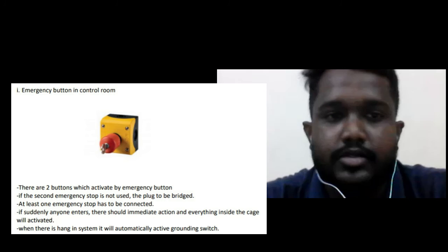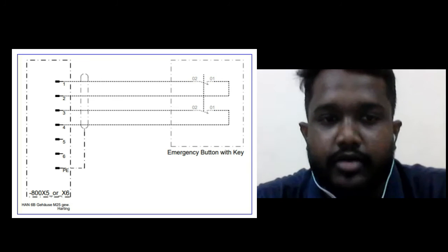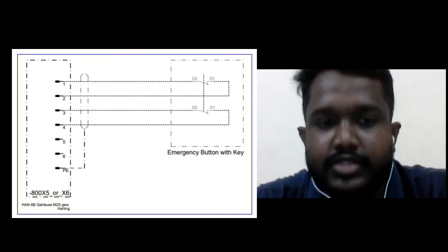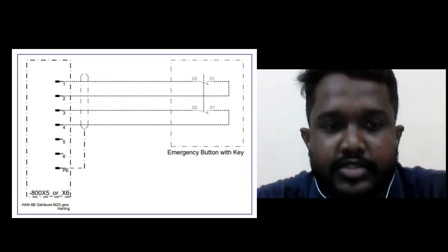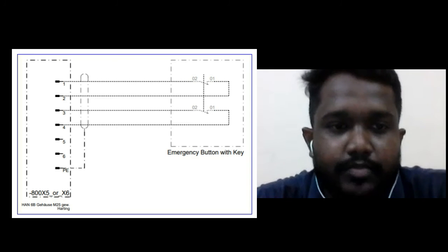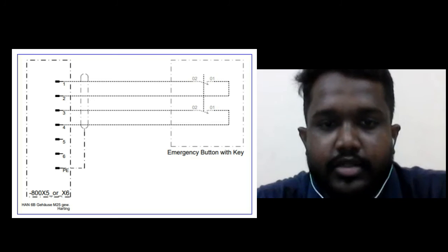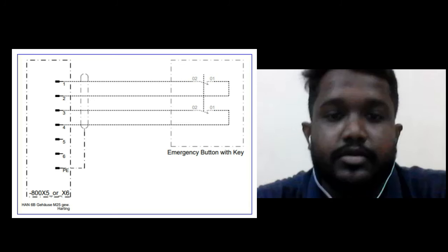And this is the two-time connection of the emergency stop in the modular kit of the cabinet. And the type of cable used is shielded cable, which must be used for the emergency connection. And the description for the emergency buttons: when pressing the emergency button, it opens the two output contacts and the input contactor of the kit of the frequency converter cabinet. So there is no voltage at the power output from the frequency converter cabinet.